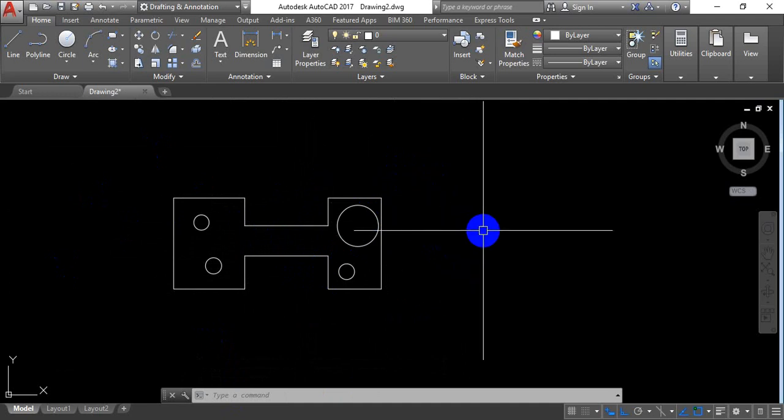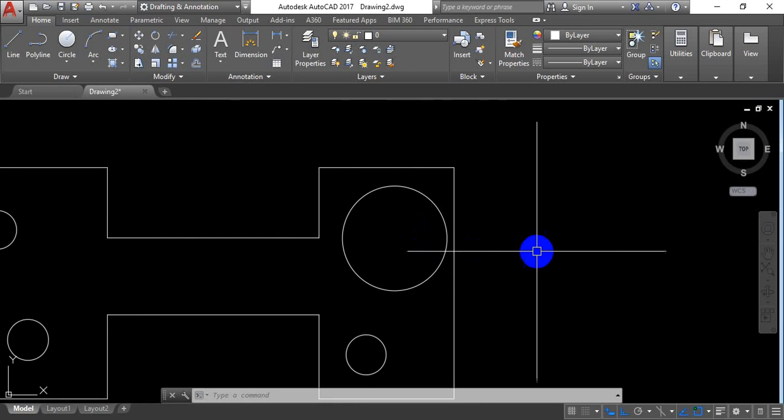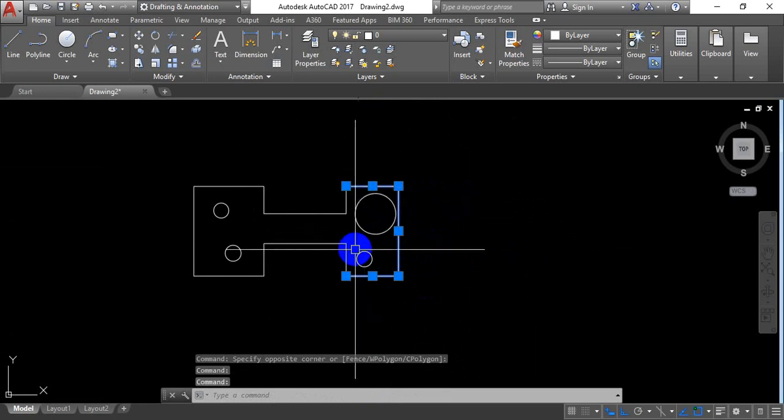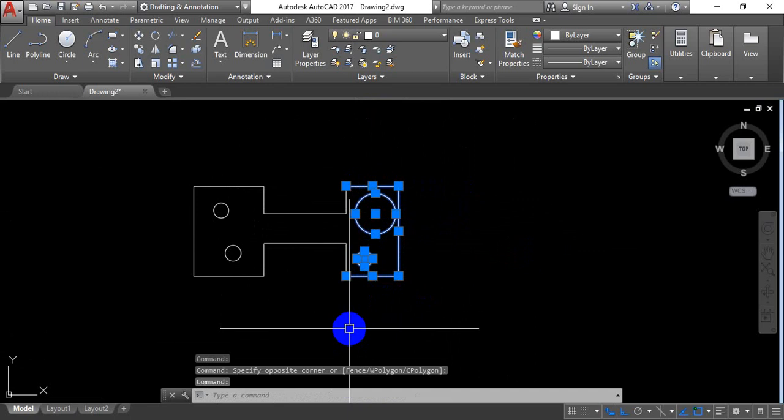So before using the stretch, you need to make sure in which direction it will go, okay. Suppose I will extend it to the right side, okay. I have taken the decision that I will extend the whole part to the right side. Now for extending the whole object to the right side, you need to change this line position, right. You need to change these two lines position also. These objects also need to change the position, right.